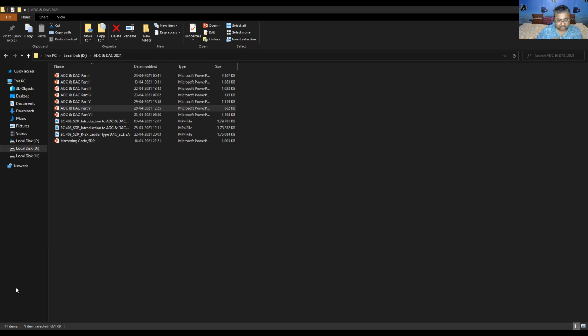So in the next clock, the output of the n-bit counter is all 0 again. This will trigger the T flip-flop, and the output of the T flip-flop will change to 0. It means the input of the integrator is now minus VR at t is equal to t1. This is the logic, and this is the mathematical expression of how the output of the Q will be 0 and it is connected to minus VR.